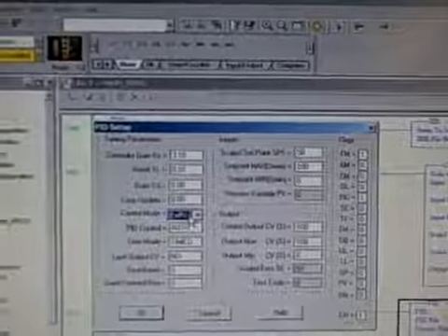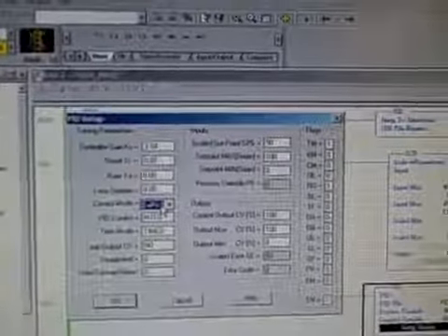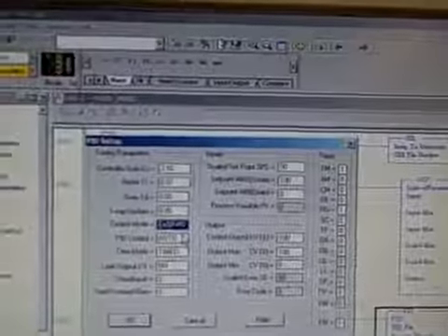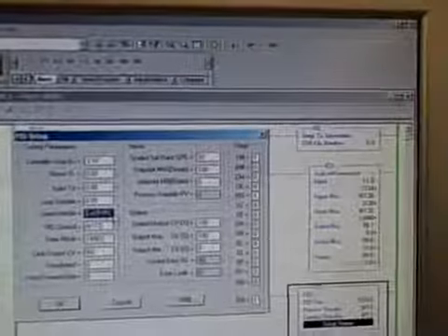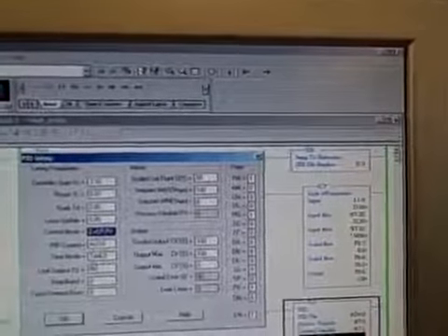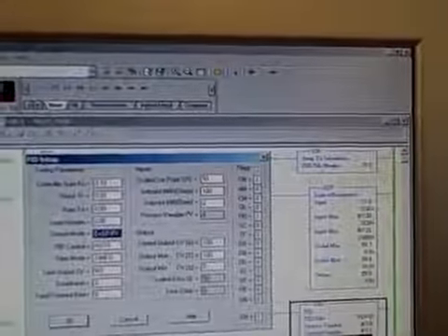If I were to hit the Enter key, this would again save that online parameter, and this would lo and behold be a direct acting controller. I do not have to save the program, I do not have to download to the PLC, I simply make my selection, hit the Enter key, and that is it. When I'm done making any other changes I'd like, I simply exit out of the program and I'm done with it entirely.